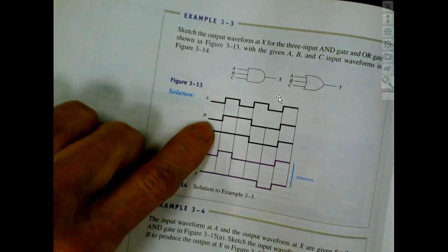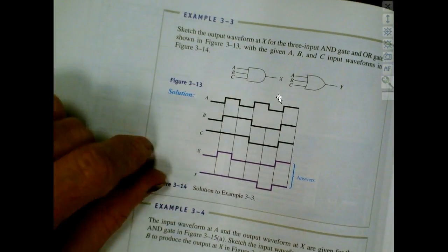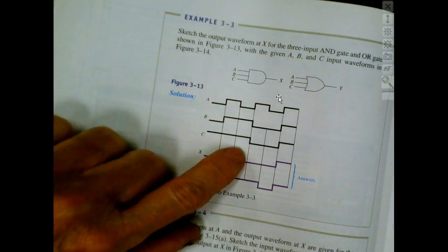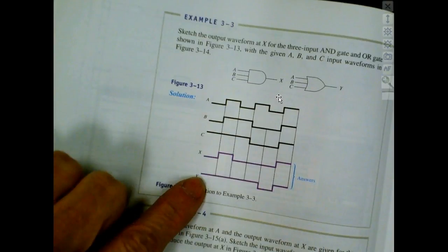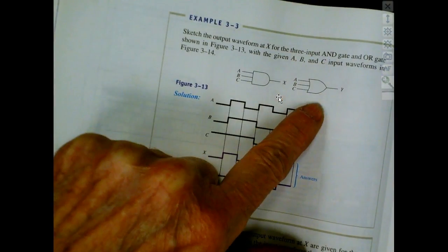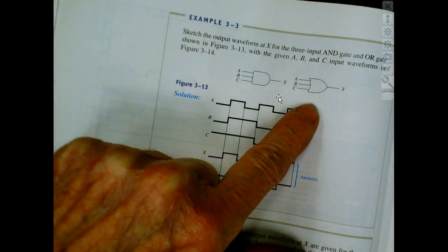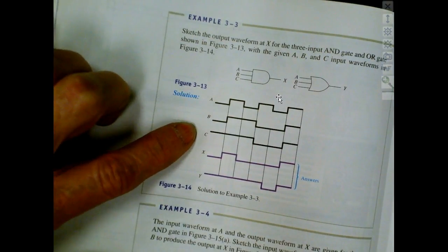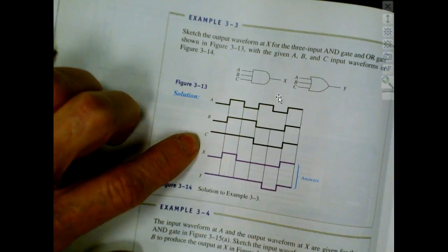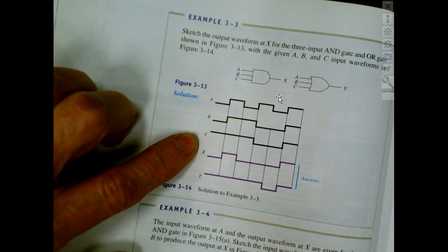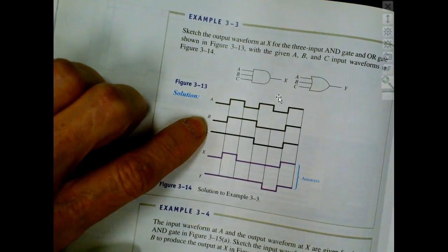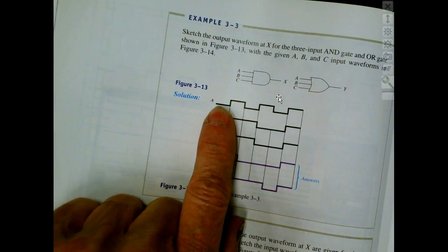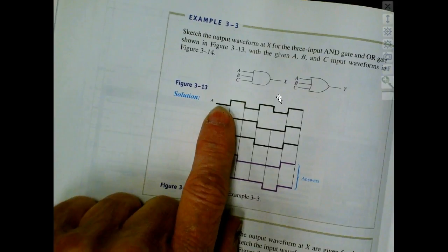this right here was the timing diagram for a NAND gate, an AND gate, and then they gave the same diagram with the same inputs for a 3-input OR gate. So notice here they label the inputs A, B, C. It's an AND gate, so what are we looking for? We're looking for all highs to get a high. So when I follow this over in this time right here, A is low, so right off the bat that means the output will be low, right?